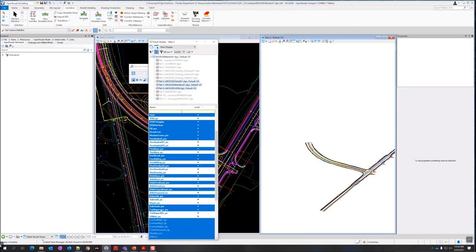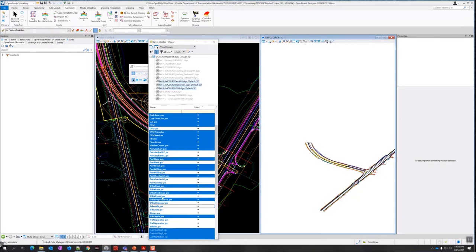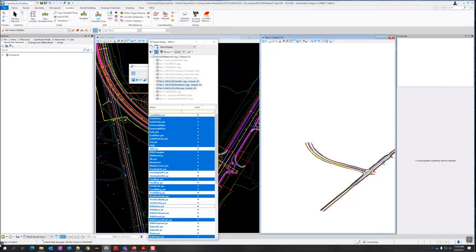So traffic separator, that's a top line. Subgrade, that's a bottom one. We need that on. Sidewalk's a top. The shoulder unpaved, that's going to be both top and bottom because it's a slope. The shoulder paved break, that's a top line. Shoulder base, that's a middle line. So it's neither on top or on the bottom. Not on either surface. The pavement overbuild, also top line.